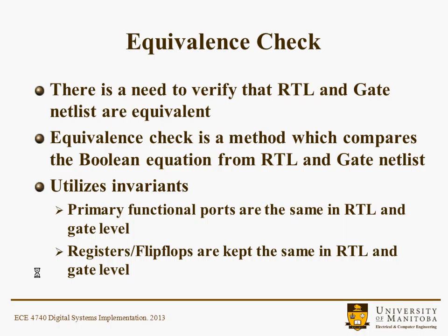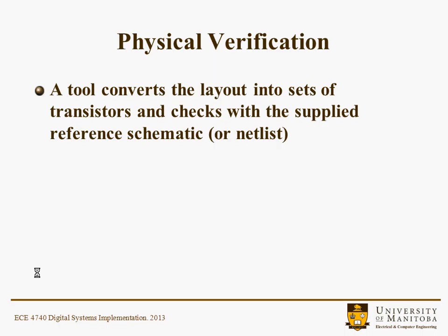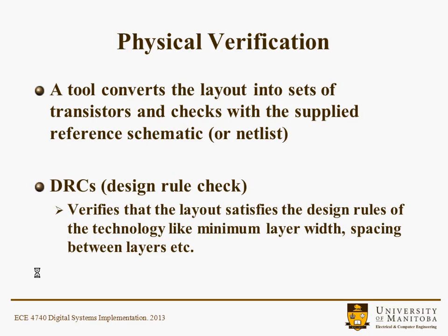Physical verification. Tools convert the layout into a set of transistors and check with the supplied reference schematic. You want to make sure that your layout, where you have polysilicon crossing diffusion, gives you the transistors that you wanted, and they're connected up appropriately so the netlist of the layout matches the netlist of the schematic.